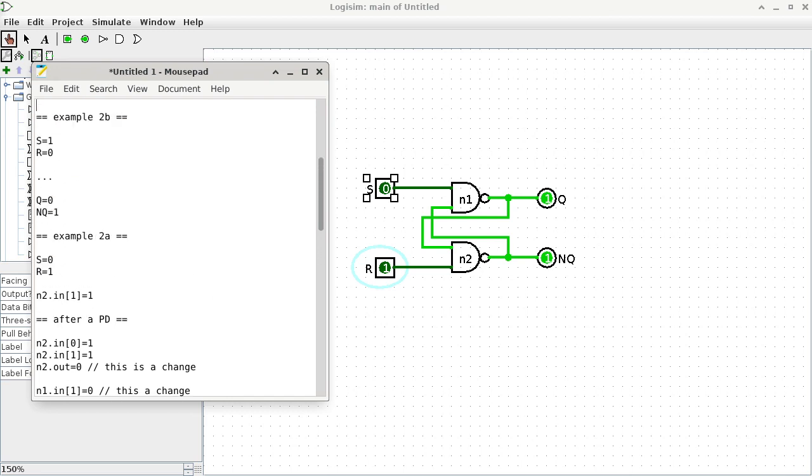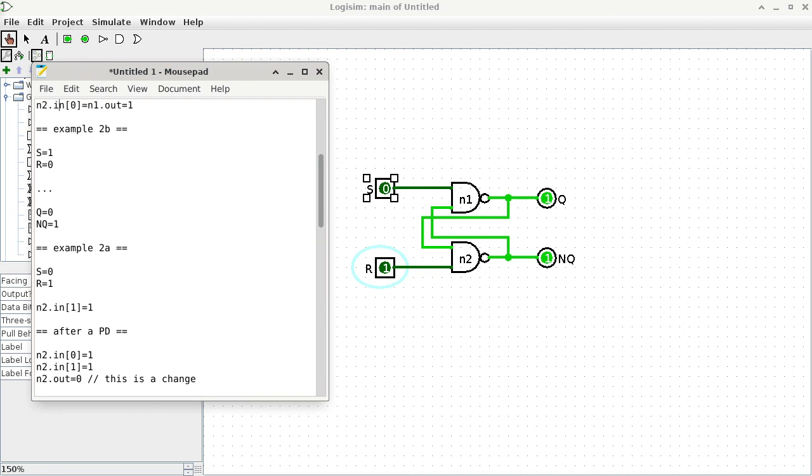So here's the fun part. What if I change, after either 2A or 2B, both input pins to 1s? Okay, so we'll examine that, because I think this is going to be the fun part, which is really important in today's lecture. So we'll start with 2B. So 2B, then we go to example 3B, where S equals 1 and R equals 1.